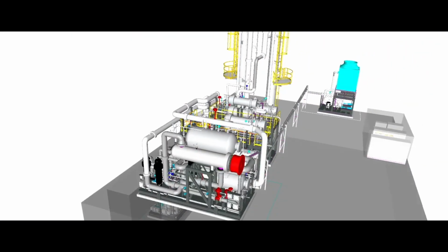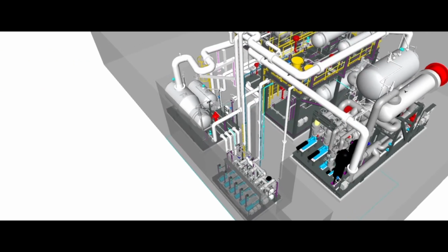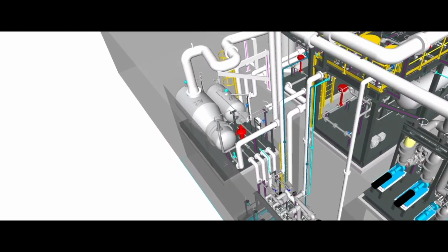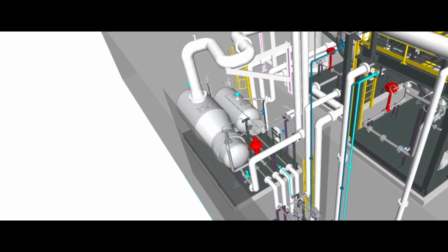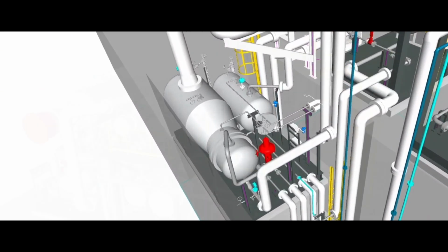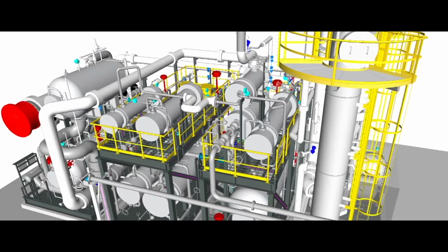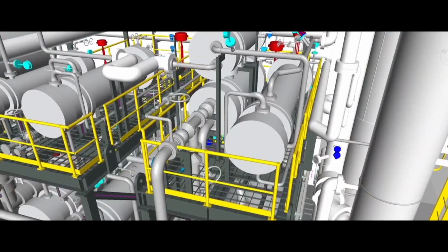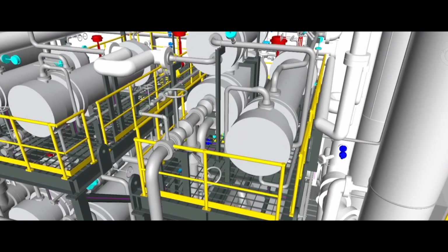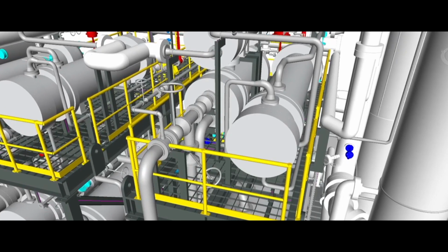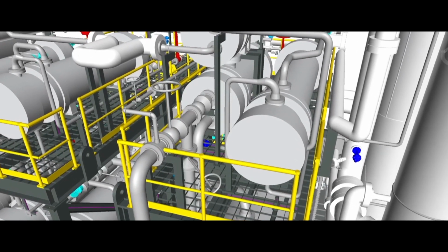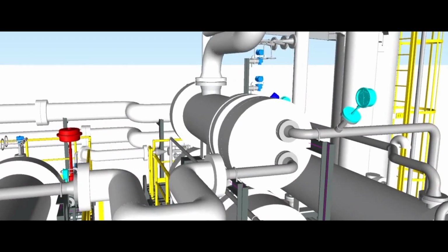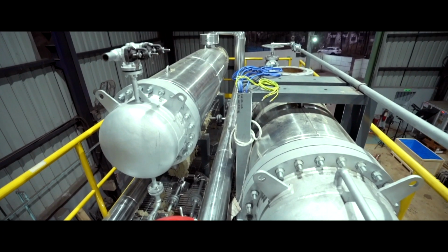The reboiler skid has a TEMA kettle-type reboiler, where the hot liquid enters from the bottom of the lead distillation tower and is heated and partially vaporized by circulating hot thermic fluid. This skid also contains the surge drum of the lag distillation tower. The OH liquid skid has 1 exchanger where feed kerosene is heated up by hot overhead vapor. The cooled-down overhead vapor is further cooled in a water-cooled condenser where phase change occurs and liquid flows to the OH liquid receiver. Before hot liquid goes to the distillation tower, it is further heated in a thermic fluid exchanger.